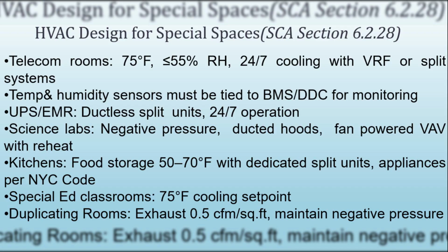UPS and elevator machine rooms require independent ductless systems operating around the clock. Elevator rooms must stay between 50 and 90 degrees with humidity under 95%.